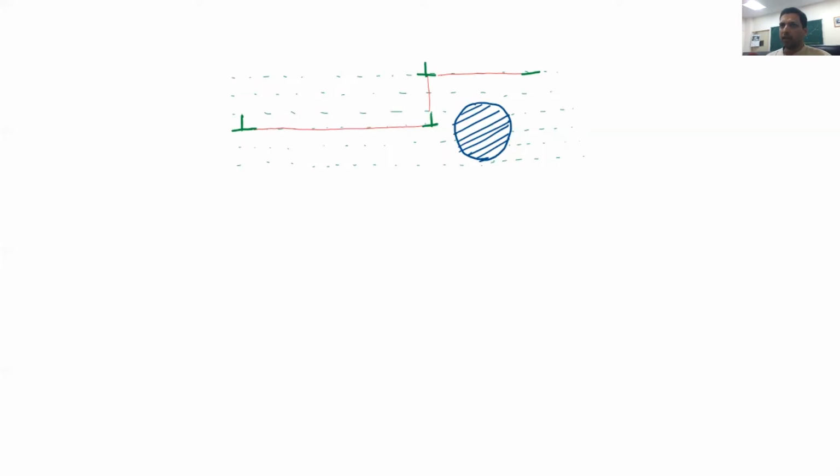However, if the temperature is high, then with the aid of the vacancies, this dislocation can climb to another glide plane. And from there again, on a particular glide plane where the glide force is sufficient to start moving it, it can move. And so here is the final position, and there should have been a green line. So this way, the dislocation is able to climb.